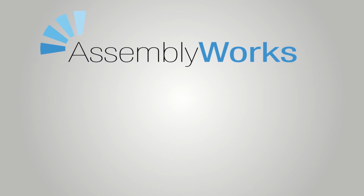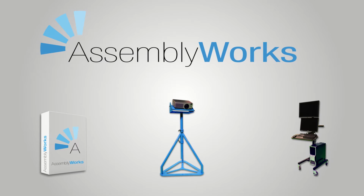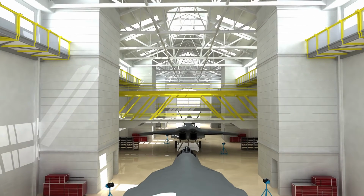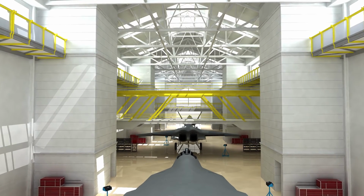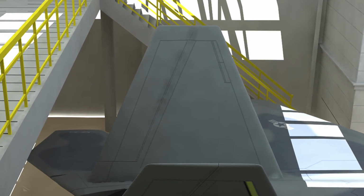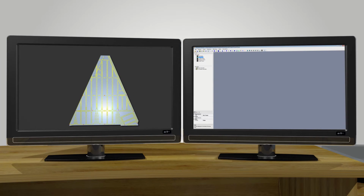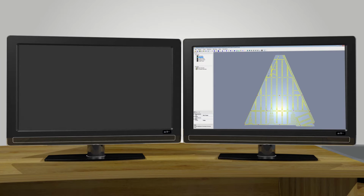AssemblyWorks is a combination of software and projection hardware used to simplify assembly processes by projecting complex 3D datasets directly onto complex parts and assemblies. Let's take a look at an example of AssemblyWorks applied to the assembly of the vertical stabilizer of the F-22 Raptor fighter jet. Relevant assembly data is loaded from your CAD application into the AssemblyWorks authoring software.